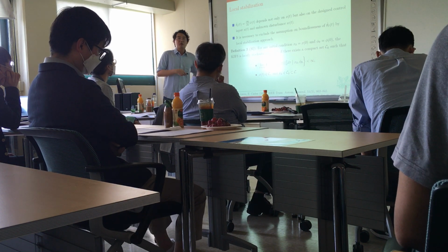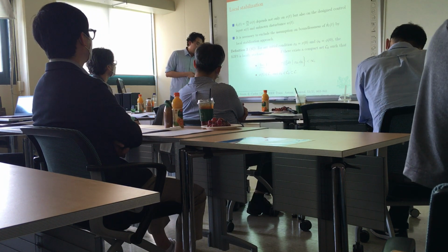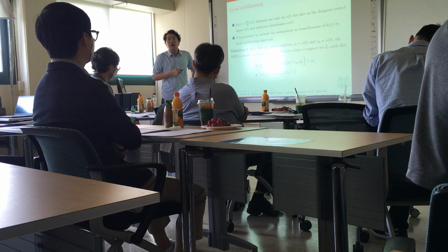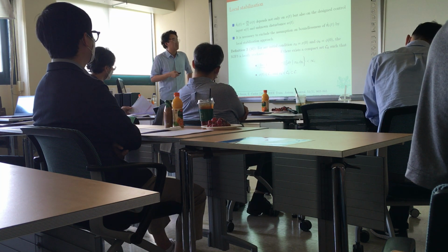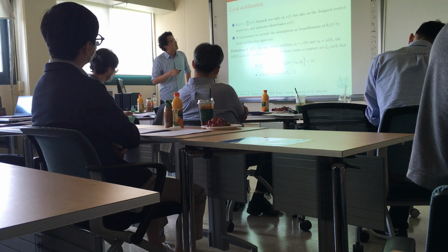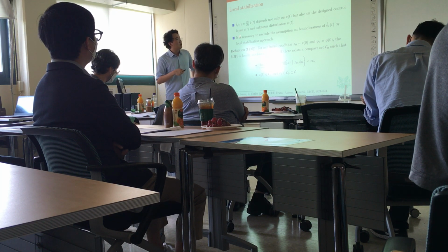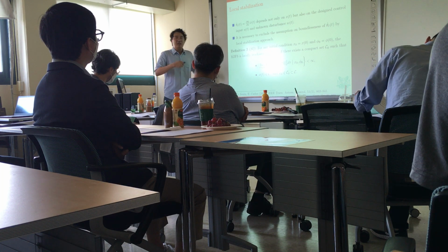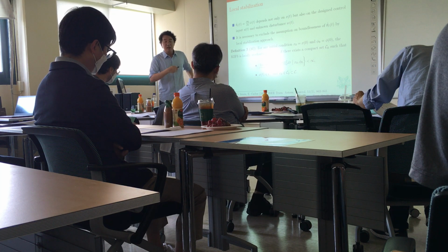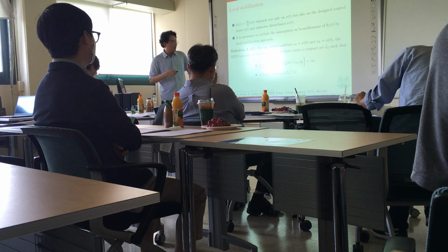Now we will introduce our main result, that is global stabilization. You can see that for the whole semi-global stabilization, we have to assume a bound on the time derivative of the membership function. But the time derivative of the membership function depends not only on the state variable, but also on the control input and the disturbance w(t). So this assumption is not practical. It is therefore necessary to exclude the assumption by using our local stabilization approach.